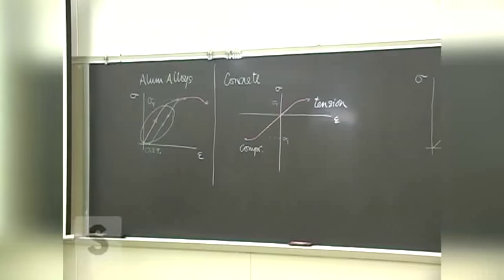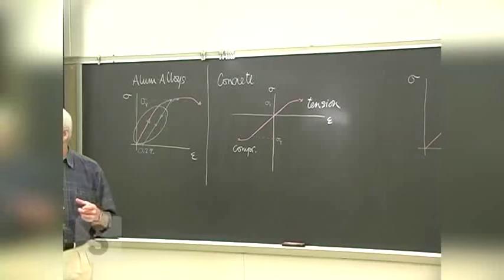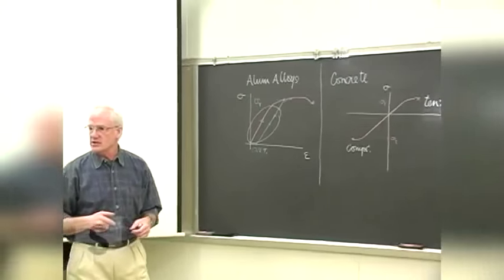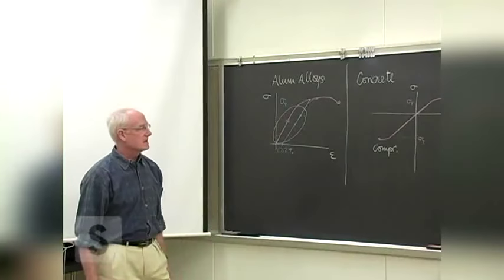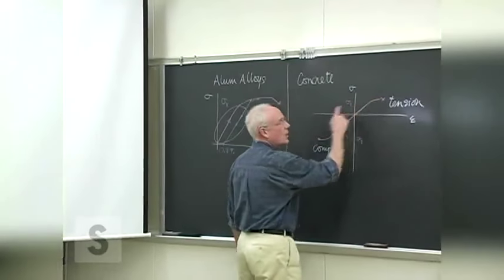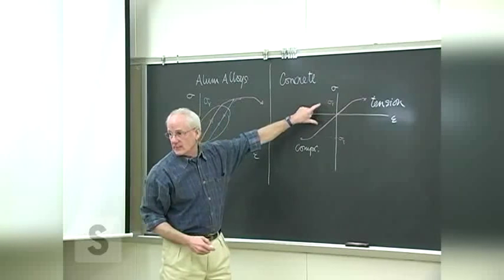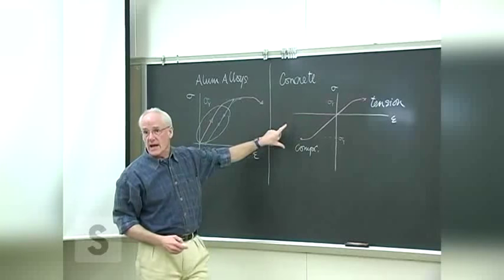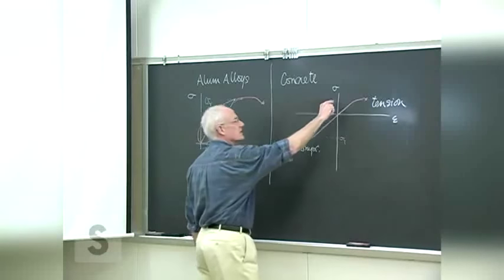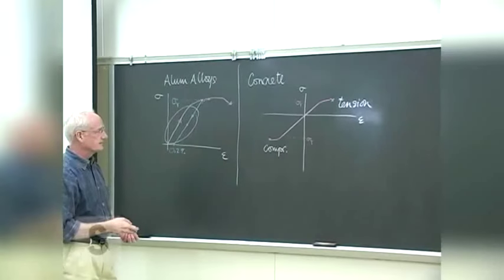There are certain materials. You can imagine certain engineering designs where a material has to cycle in and out of compression and tension. Concrete is not real good for that, partly because it is so weak in tension. This can be a factor of up to almost somewhere around 8, and it's true for wood as well. The difference between these two is almost a factor of 8 in some concrete mixes.